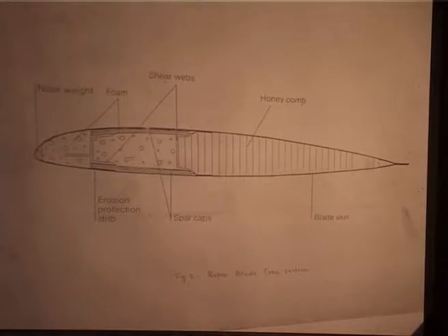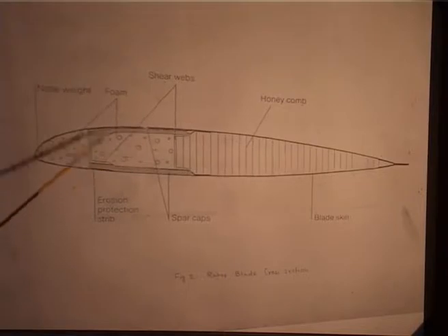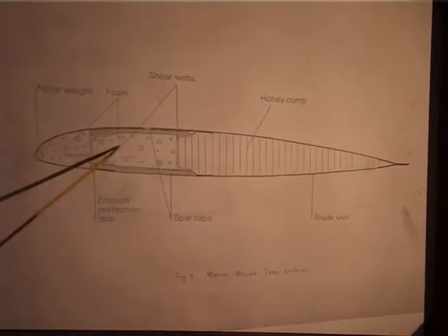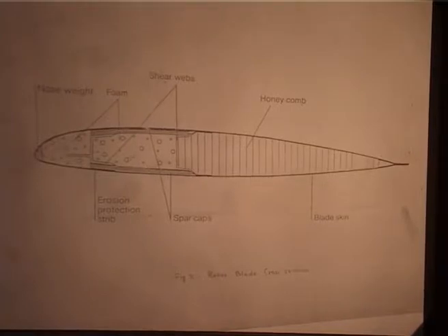I do not think in this course we will be able to learn that. And then of course, your aerodynamic center is at 25%, take it as 25% because it is subsonic. Then you also make sure that the shear center is at 25%.